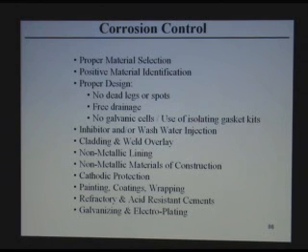Otherwise, you end up with a catastrophe later on if you put it in service. This was required based on a lot of incidents, fires, and leaks, where people died because they used carbon steel where you have to use 5 chrome, and you end up with corrosion, leaks, fire, and disasters. So this tool is very important to avoid that.